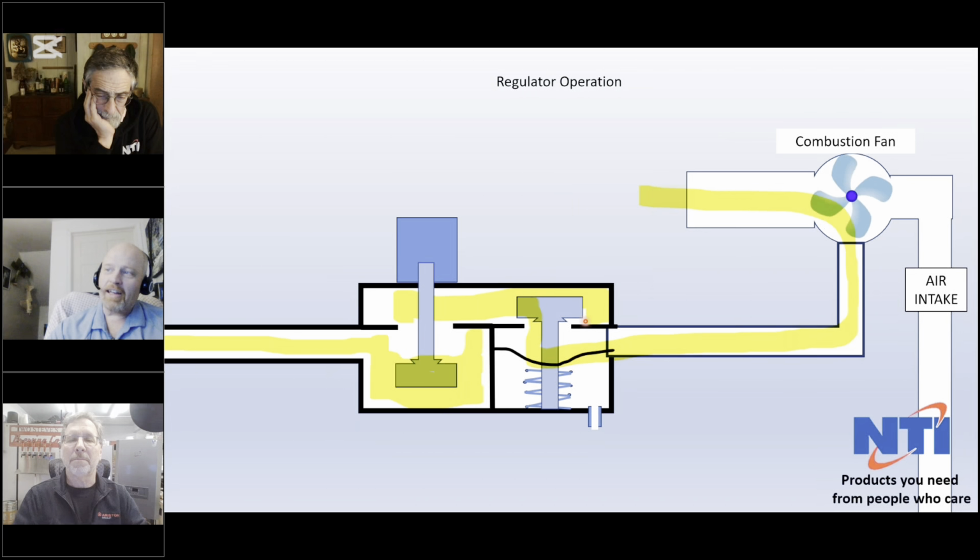This little plunger here is controlled by the vacuum, and you can see these two holes up in the top here. And you'll notice those holes correlate to this cavity here, which is directly connected to the outlet where the blower would go. So as our blower draws more air, it's going to pull a vacuum, pulling this diaphragm in the downward position.